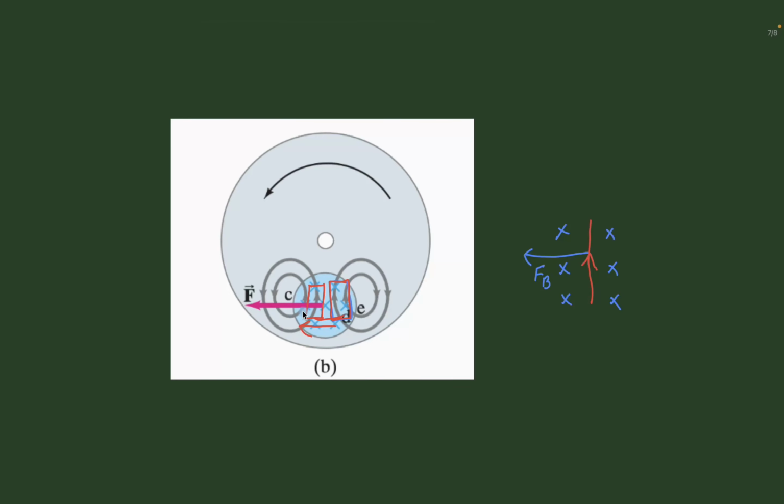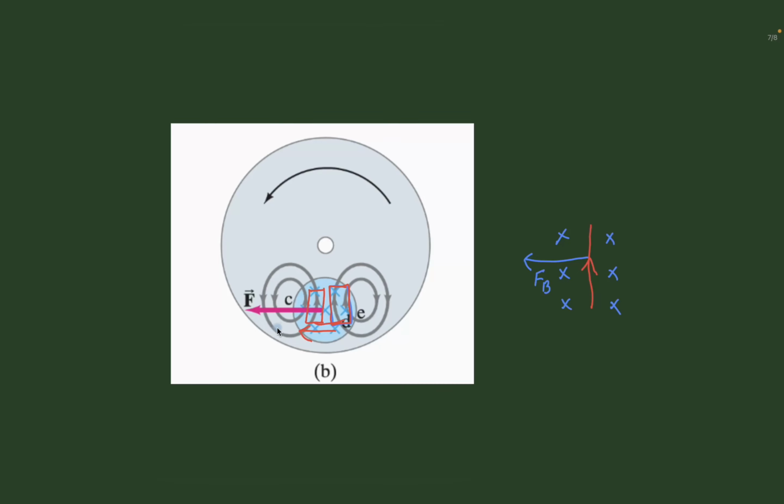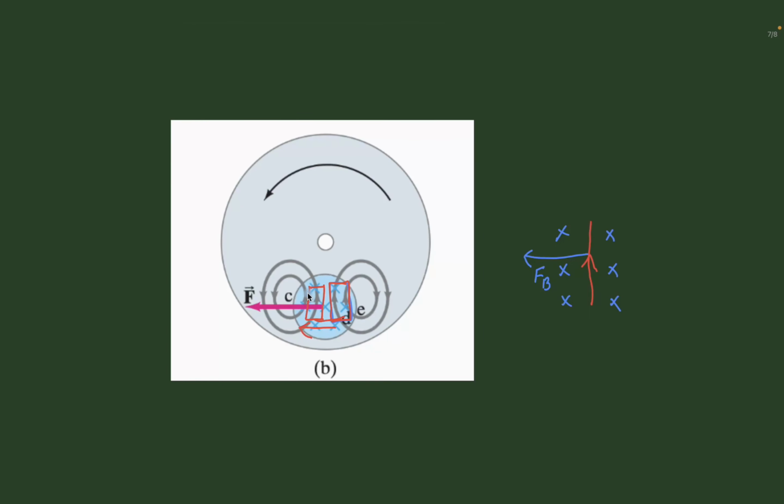There is no conducting wire, but in the conducting plate or sheet surface area itself they will form the loops. And because these eddy currents are formed here, that section of the sheet is going to experience some opposing magnetic force, which will convert the mechanical energy into thermal energy in this case.